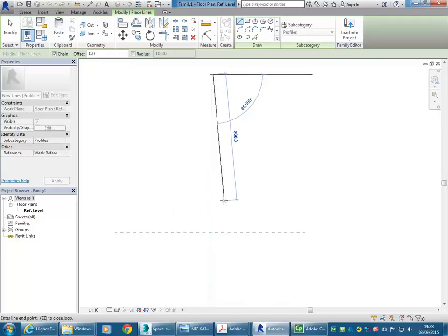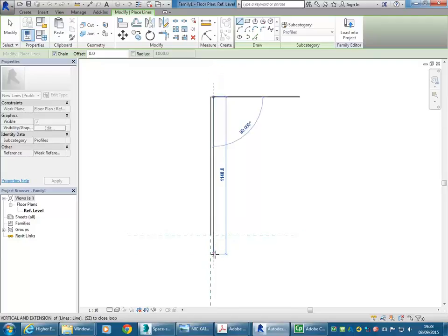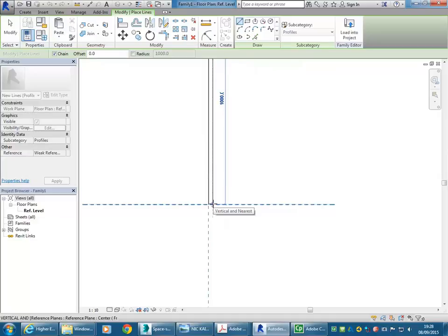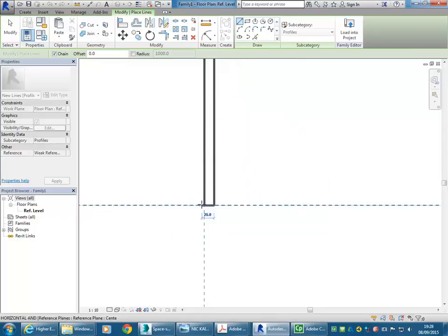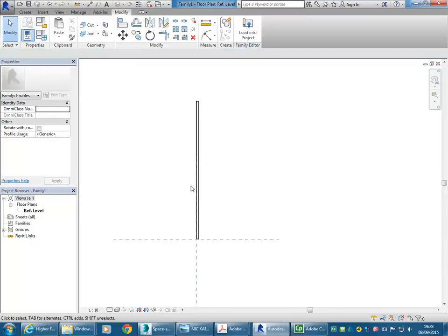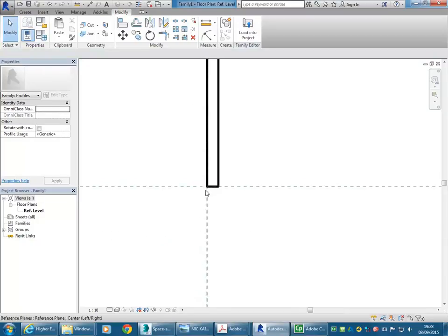And so then coming down, I'm going to go down more than a metre because I want this glass panel to go below the stringer. And oh no, sorry, I've got a stringer. So I'm just going to keep it simple and go down to the baseline there. I'll show you how to extend it afterwards. So then I'll bring it across. So really simple. I've basically made a rectangle that's 1 metre by 20. But importantly, it's from this intersection here that I've measured that.